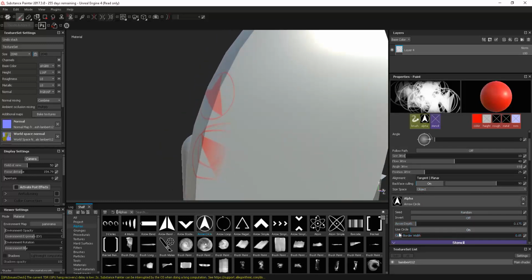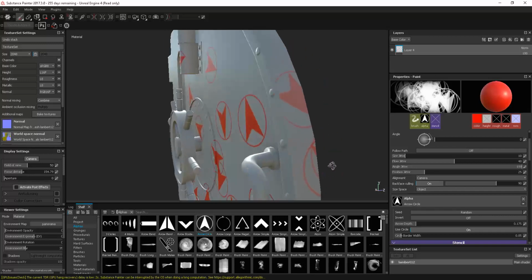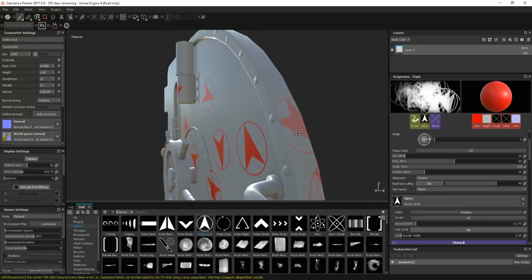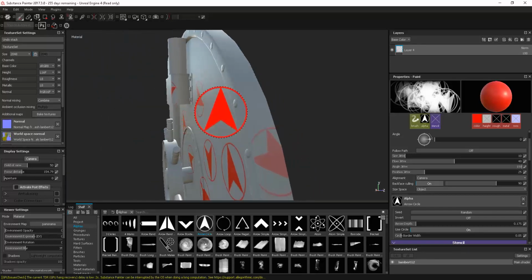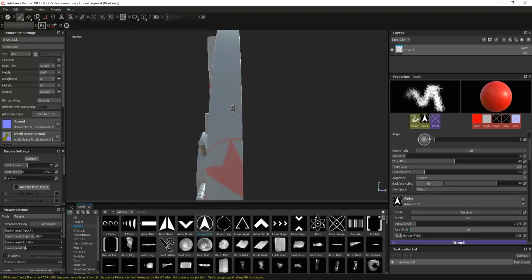The other option we have in there is camera. So with the camera, this is now not going to be based on the normals. It's going to be based on the position of the camera. So wherever I'm painting this, you can see now that it's not rotating to go around and follow the object normals. You can see when I change the camera around, it's positioning it this way. So if I wanted to put something perfectly on there, let's just change the size of this. Okay, I can get the camera into the right position and then place that where it needs to be.